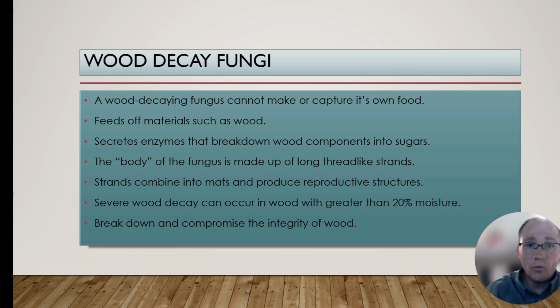My advice is when it comes to structural issues, I wouldn't stay too much on that with people because most of us are not structural engineers and we really need to think about what we say to people. And if we do think there's a major structural issue, we might suggest that they hire a structural engineer. But I do want you knowing that with severe wood decay, it's usually going to be greater than 20% moisture. So as you're going through crawl spaces, and we're going to even talk about moisture meters, the amount of moisture and percentage is going to be a big deal on telling you kind of what you're running across and what you can do about it.